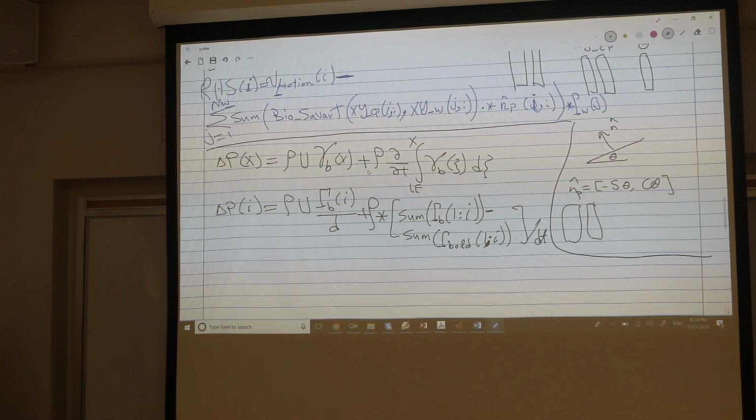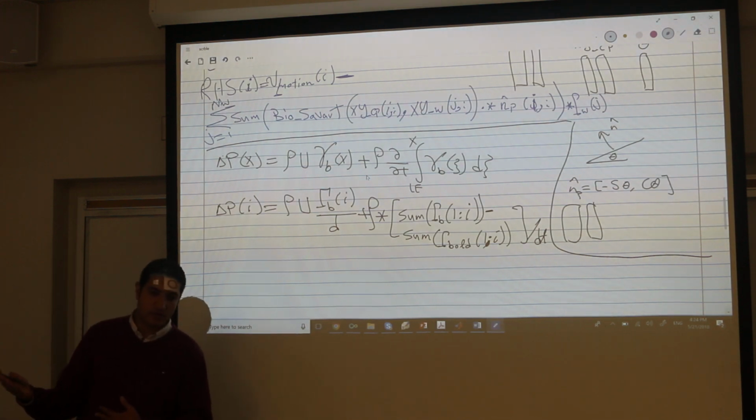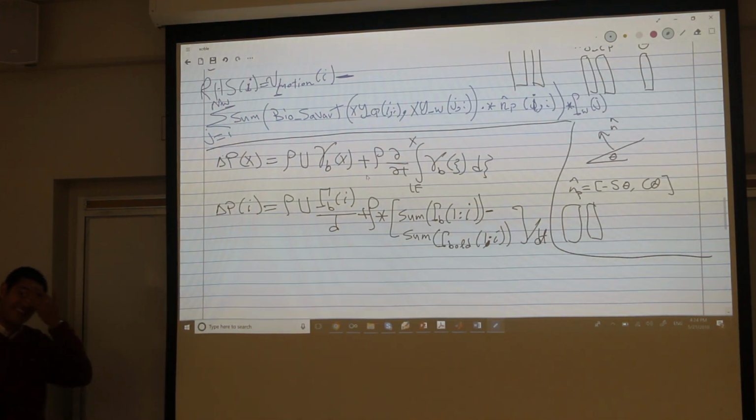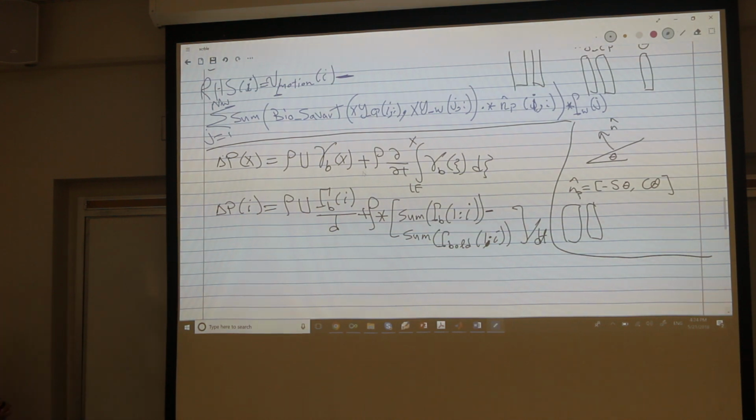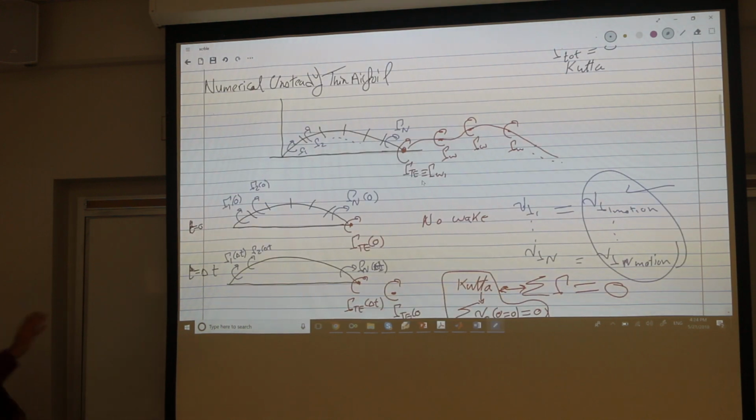This tool is very useful. If you want to simulate a maneuver, I will not go and do it with DORSAL, I'll just do the UVLM. If I'm doing stability analysis and aeroelasticity, I'll do the state space model. It's very useful, very practical. If I'm doing just a simulation for a maneuver, I will do the UVLM because it's more accurate than the state space model. It allows for wake deformation. The wake at the end of the day will be freely deforming like here.